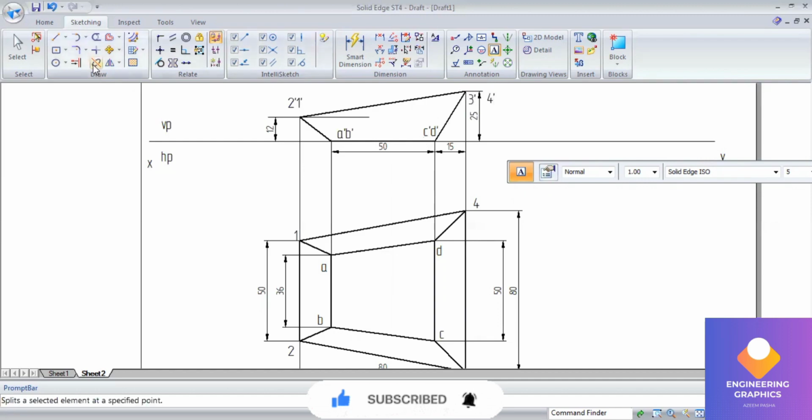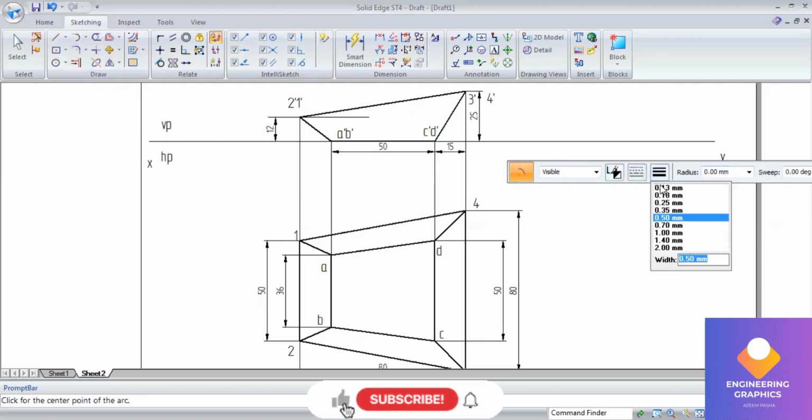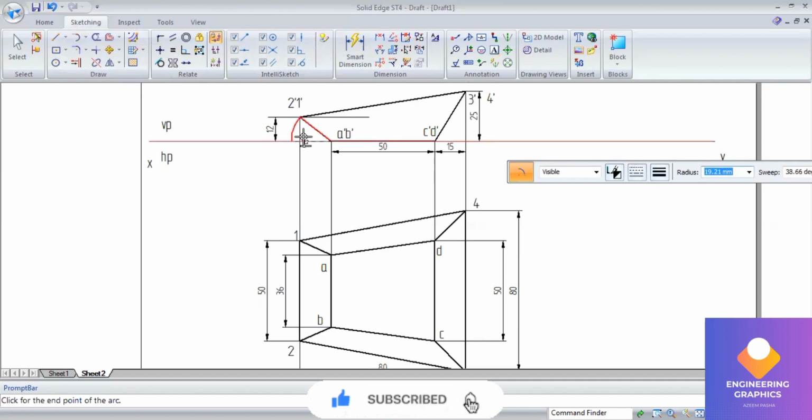Okay, now taking the front view edges, so we have to draw an arc. Taking the length from A dash to 2, cut the arc till XY. The same way we have to do it on this side also. From C dash to 3, measure the length and cut the arc.